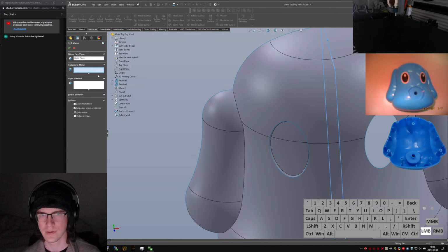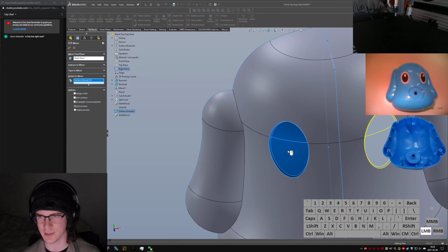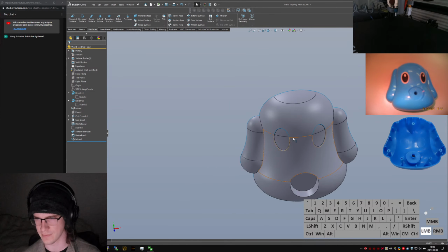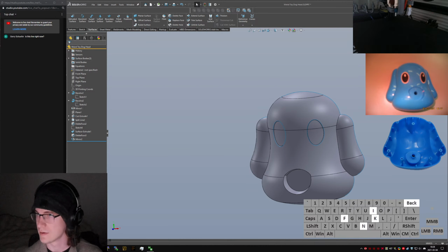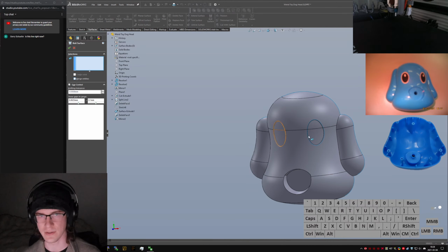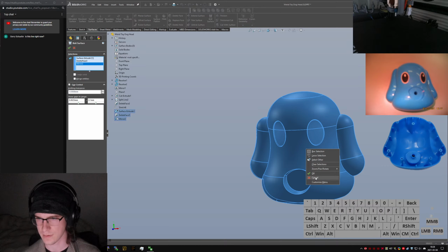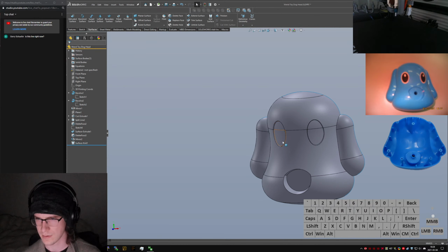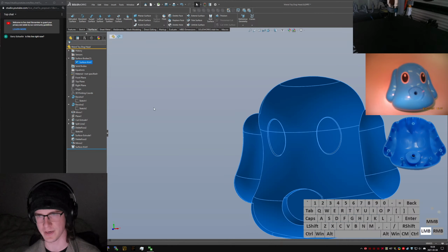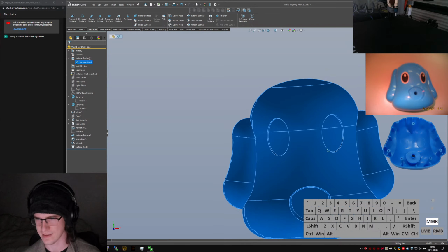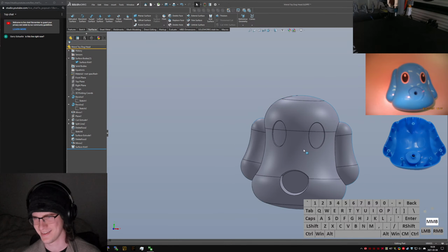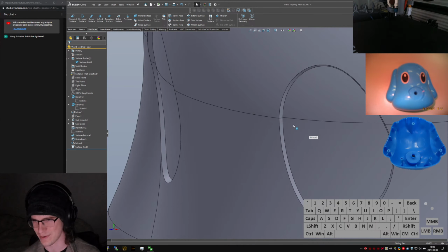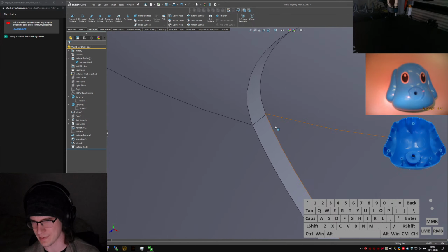So, right plane, we're just going to mirror the resultant body, and that'll put that in the right place. Now we can bother with knitting all this back together. Okay. Just picked all three there and knit them all back into one, so now I only have one surface body to work with. Ooh, that looks ghastly. Wish I could steepen up that draft a little bit, but I'm not really sure that I can.